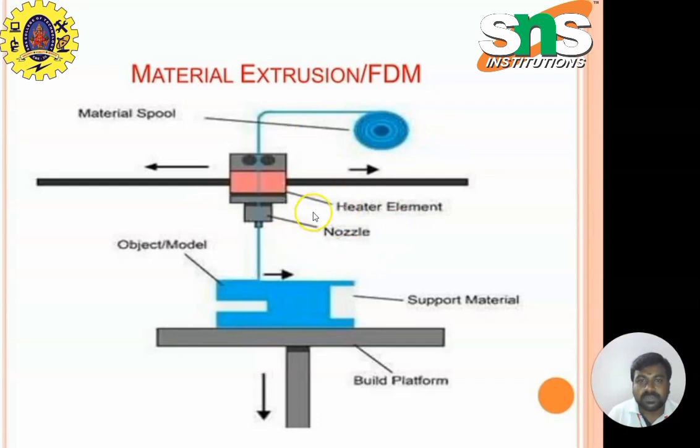So this is the representation of fused deposition modeling. In fused deposition modeling, the raw material is in solid wire form. Here PLA or PLA plus, that is polylactic acid plus, and ABS, acrylonitrile butadiene styrene, materials are commonly used as the raw material. It is in the form of solid wire. This solid wire is inserted through this heated nozzle. Here the nozzle temperature is around 275 degrees Celsius because of the melting temperature of the raw material.